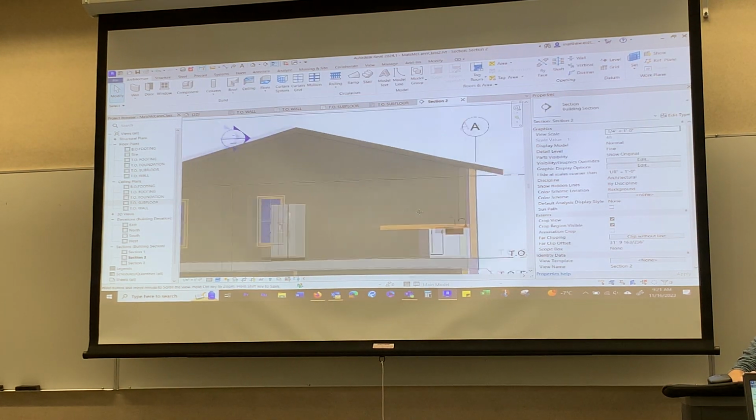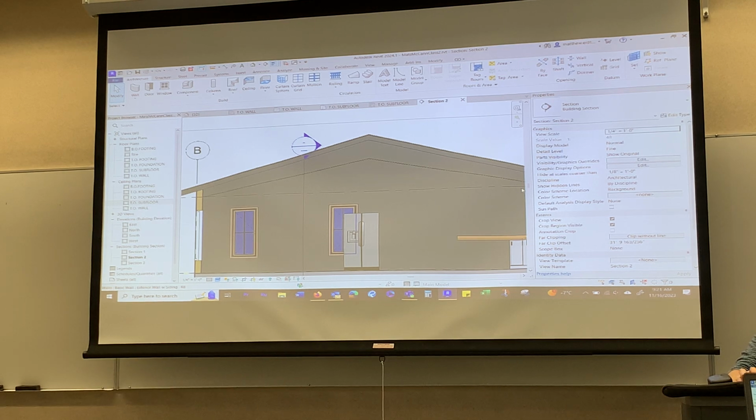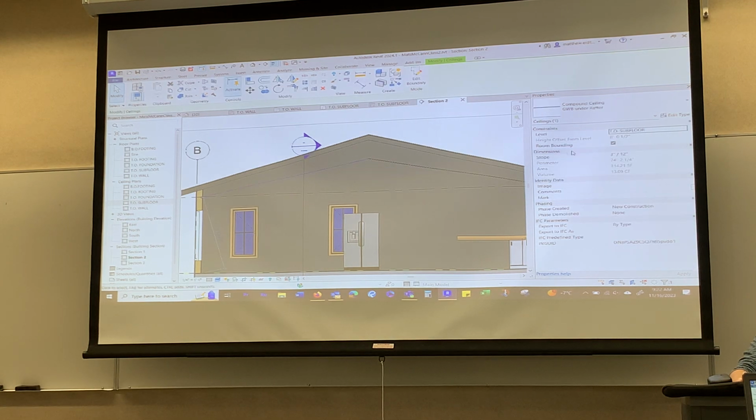Ah, that worked. Yeah, I did this last night, and I have no idea why, or yesterday, and this was a foot off. I measured it was way up here. I went back and checked those constraints, and they both said 8'1" offside. So if yours doesn't line up, and you swear that you're right, you can click on it. This is grayed out right now. You kind of have to go back into sketch mode and edit the boundary because it was drawn in sketch mode. You can't edit it here.